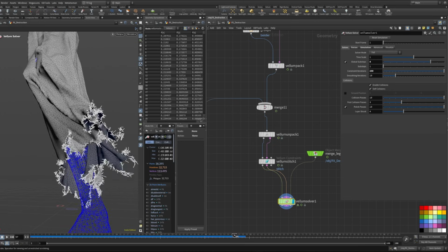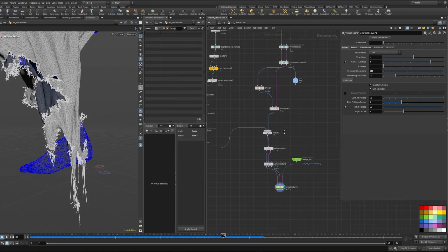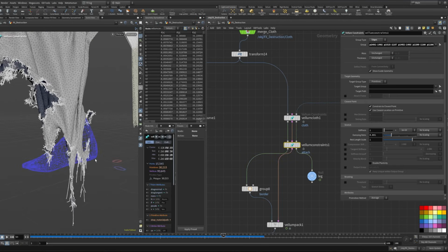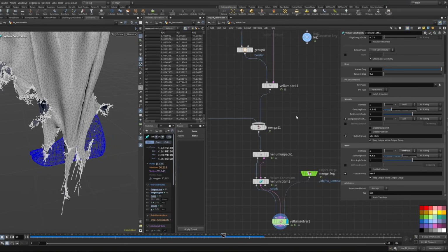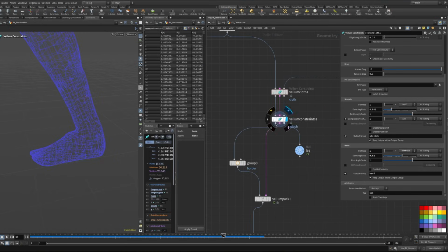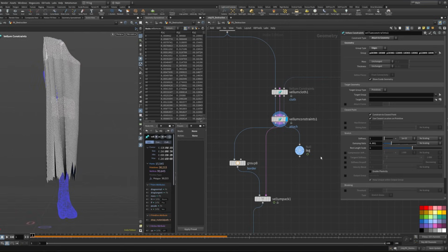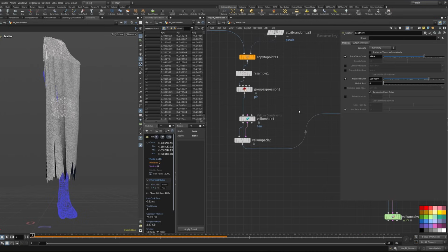Now let's watch the result. And we got a weird bug over here. To fix that, we need to change some values in the attachment, and maybe also here in the Vellum cloth. I think I will change some values in the attachment as well. So maybe something like this here. Good. And I maybe also want to change the count here to around 2200.